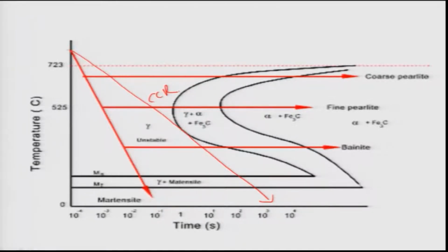So that is possible. The cooling rate which I used in the earlier plot is no longer required. I can cool it this much, or I can cool it even much slower than that, and I can still form martensite. So one way of attaining a lower cooling rate to form martensite is to alloy, to make the steel contain more alloying elements like manganese, or even chromium. This is widely used in the literature. You clearly see that when you shift the nose to the right side, it gives you a lot of advantage. Let me first remove these lines and then show you.